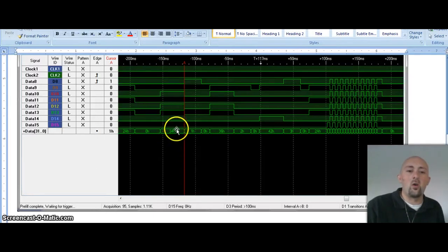And then after a while, we have some more latch controls that you wouldn't see on the data bus. And then over here we have an address that's being put out to the data bus to go to the address latch. And then here we have latch controls that are occurring, but the data bus has a 0 on it. And then here we're going to the actual output from the EEPROM. And then again, address, latch controls, output, address, latch controls, and then here we have the output from the EEPROM, and the 2A is the ASCII value for the star.